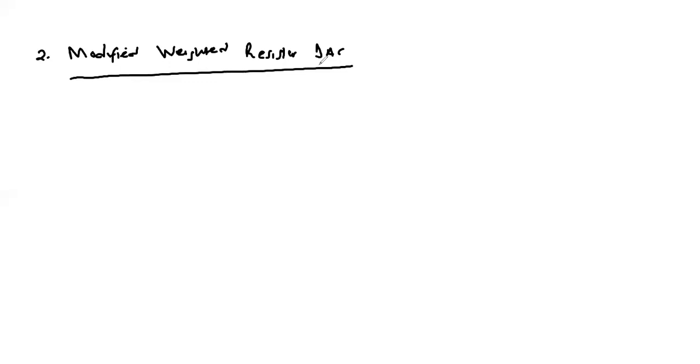The modification is carried out so as to accommodate the large number of bits without a consequent spread in the resistor values. So we want to increase the number of bits, but at the same time, we control the spread in the resistor values. We will illustrate this with an 8-bit modified weighted resistor DAC, which would look like this.